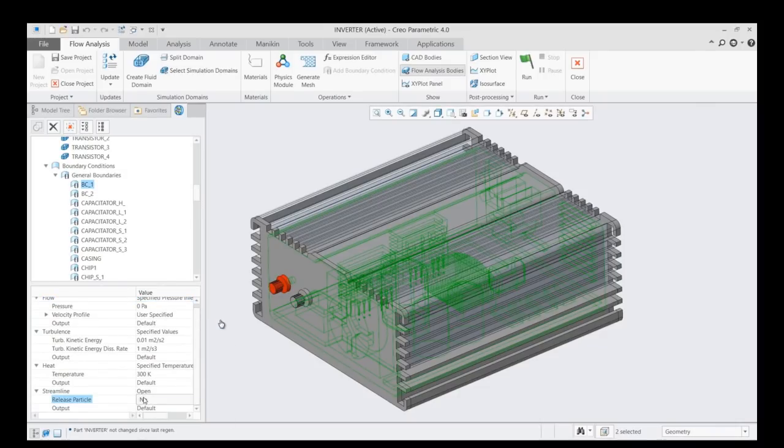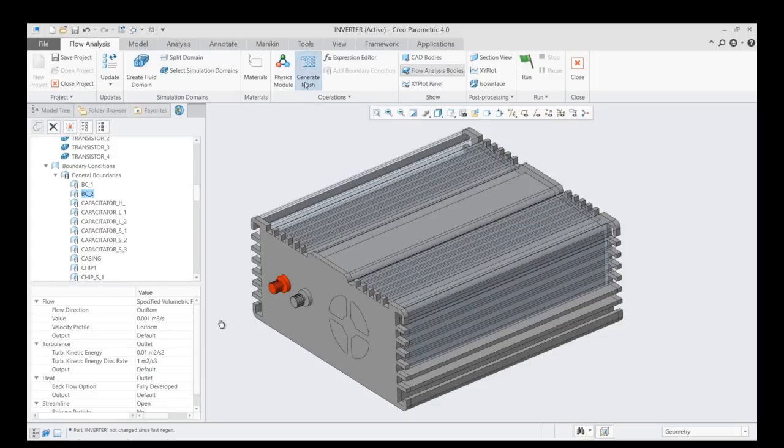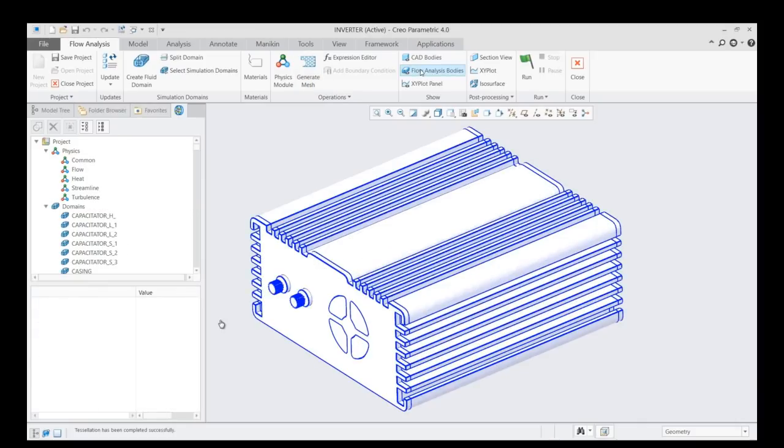Next we need to set up some boundary conditions for the actual cabinet in which all of these components sit. So at the back I've said it's just going to be open, and on this front face I've said that it's going to have an outflow of 0.001 cubic meters per second. So let's generate the mesh. An important thing when you have both fluids and solids is to have this boundary mesh, the interface mesh, between the two components.